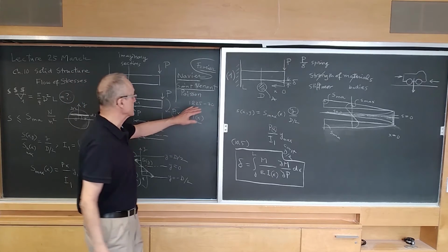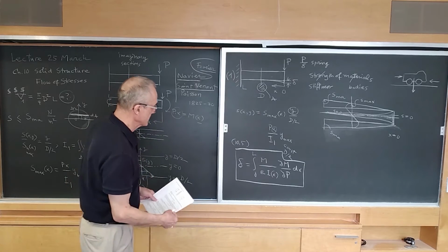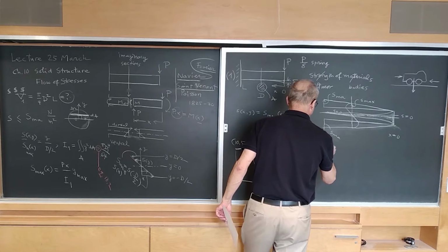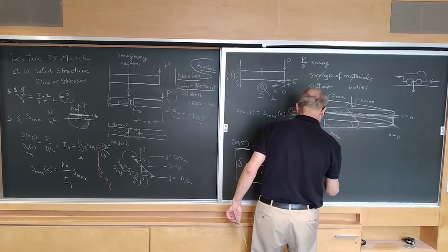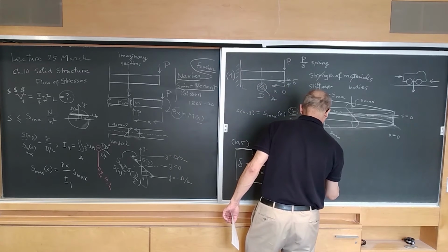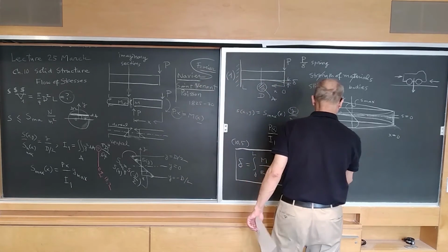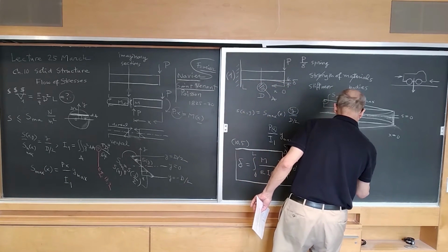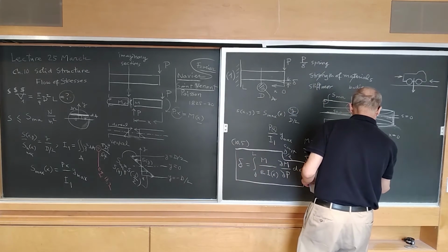basically 4 times. The first time is for this design. Because, as I said, M is Px, the partial of M with respect to P is x, and in our case, I is a constant. For this case, the delta, the deflection at the tip, turns out to be P L1 cubed.